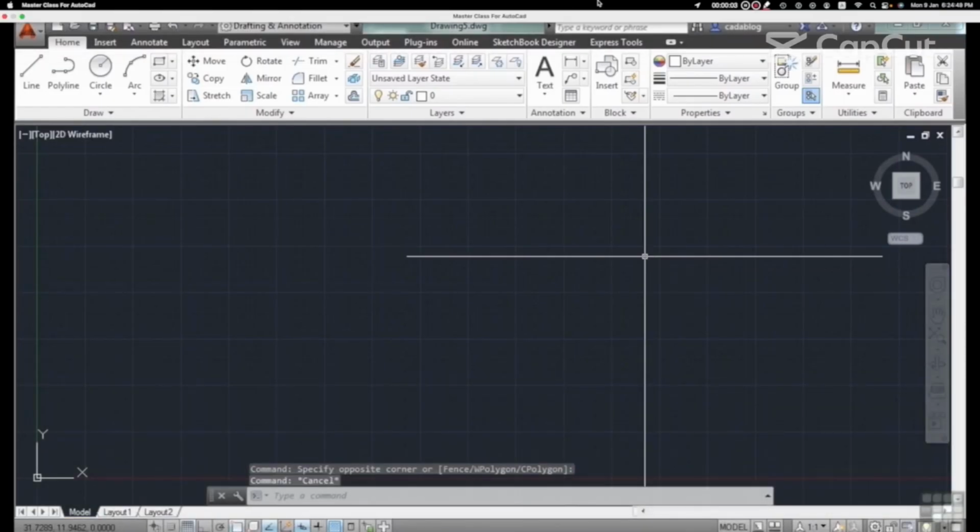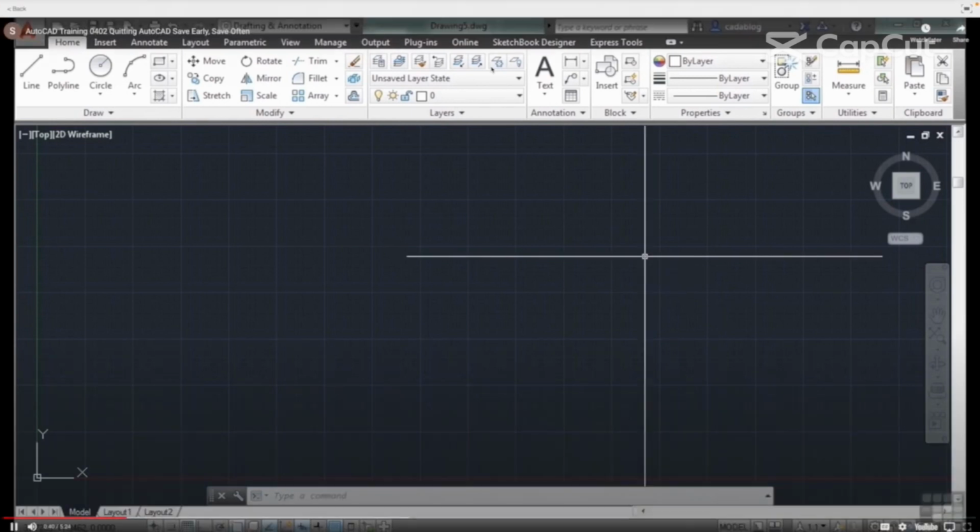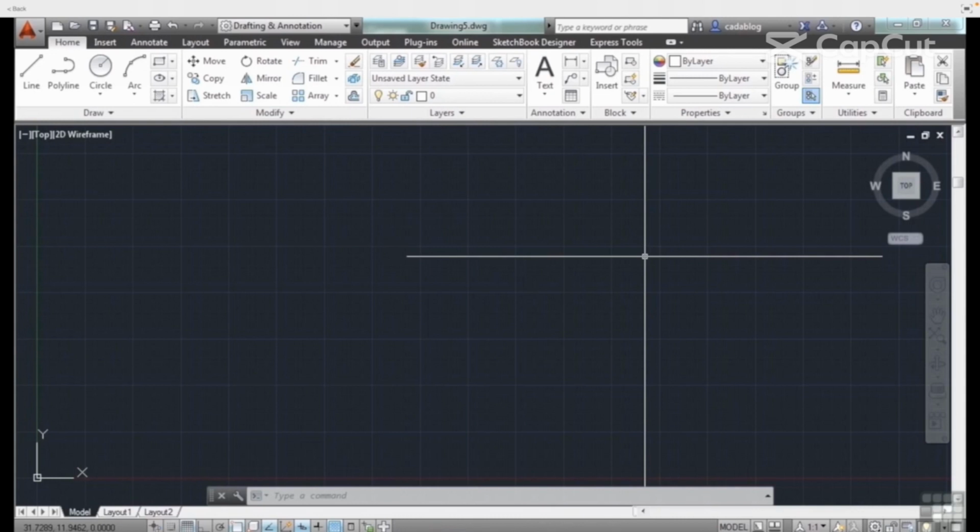Close or exit. They're similar yet different, of course. If you have several files open and you close, then only the current file will go away. On the other hand, if you type in exit, every file will close, and so will AutoCAD. So close is to close your file, the current one, and exit is to leave AutoCAD, therefore closing all of your other files. There's also a close all command that will shut down all of your files but leave AutoCAD open. Just type in close all.